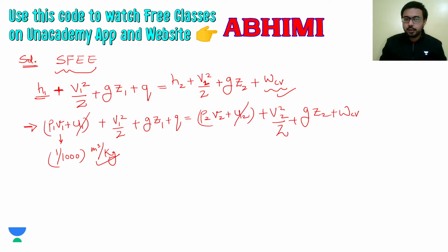I totally had the confusion when I was doing this question today in the class. I mistakenly took that. Then one of the students pointed out, sir, the specific volume was written wrongly. Then I checked it, and it was going to be this different specific volume. For water, take it as 1 by 1000, that is 1 by your density. And let's do this question now.